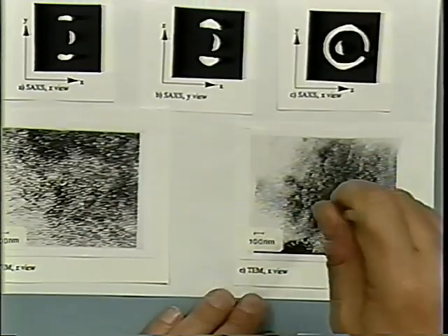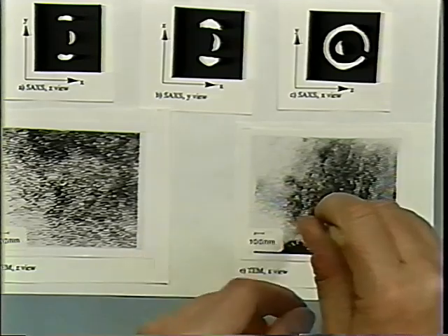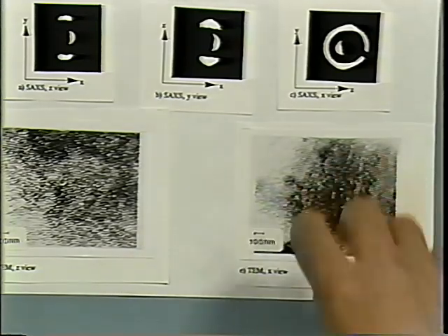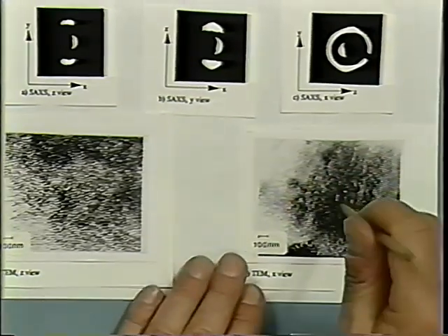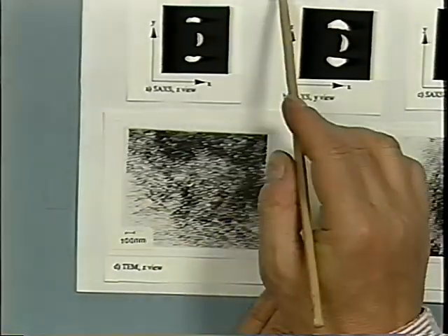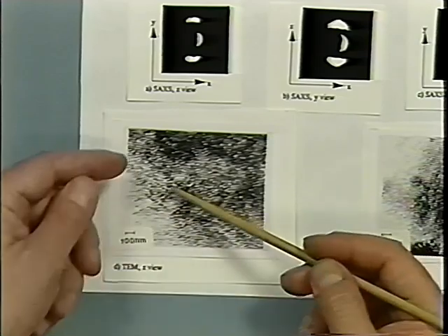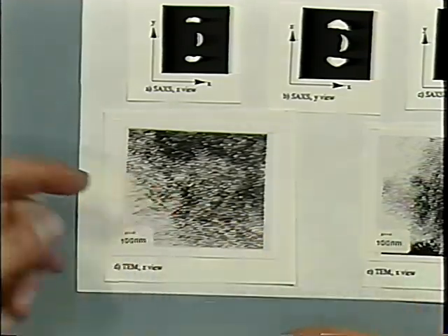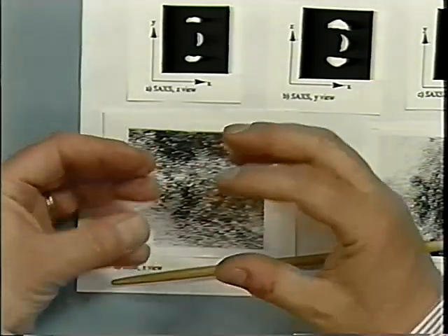This is the micrograph, actually looking down in cylinder direction, and you can see that the hexagon planes are not uniform, and this causes interfaces, and that's why the side view of our sample is kind of wavy, because the cylinders are aligned, but we are generating all those interfaces by reorienting the sample. That was at a stretching of 4. The sample of initial length 1 had been stretched to a final length of 4.